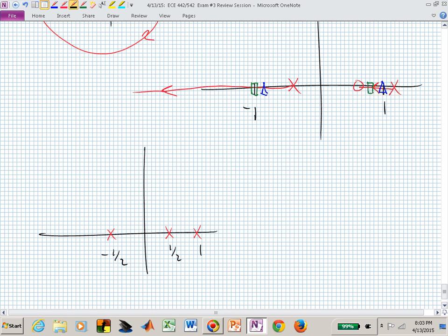How many zeros at infinity do we have? 3. So where are they located? They have to be located such that if those 3 poles went to one of those root locus locations, their angles would sum up to -180. Which means what?